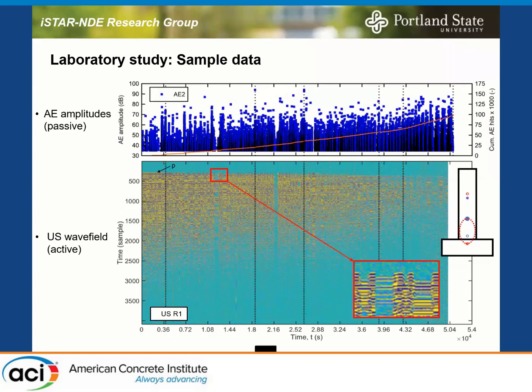There, the problem I have found is coupling. Depending on what you do, especially for the coda portion, really small changes in the coupling just throw everything off. If you just have humidity changes, or if you use a bonding agent that dries up, it will affect everything. The embeddable sensor is about 75 millimeters long and has a diameter of 20 millimeters.